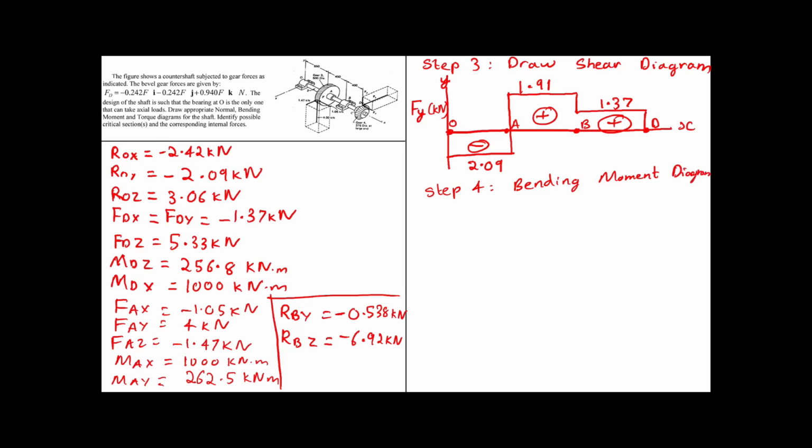Okay, so similar way we'll draw the axis, and then we are going to draw the moment about the z-axis. Now why is this z-axis? The force, the x-axis and y-axis, if you are choosing this for the shear diagram, the axis which is not present would be the direction of moment.